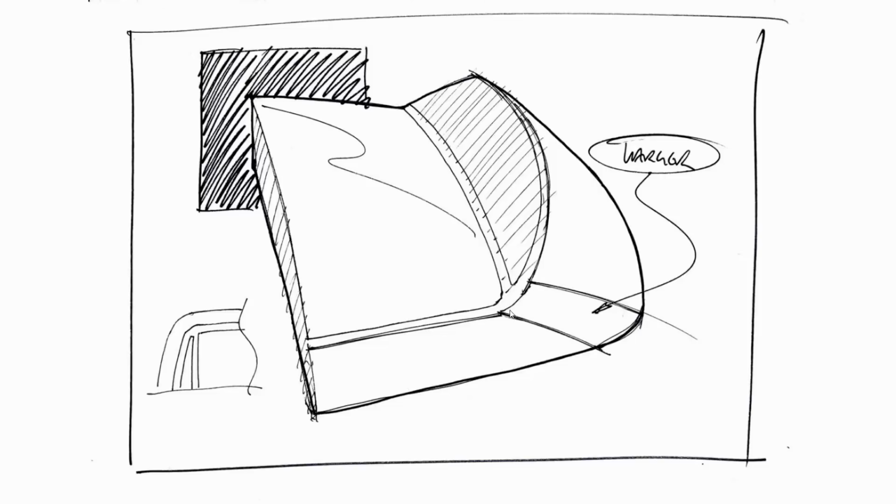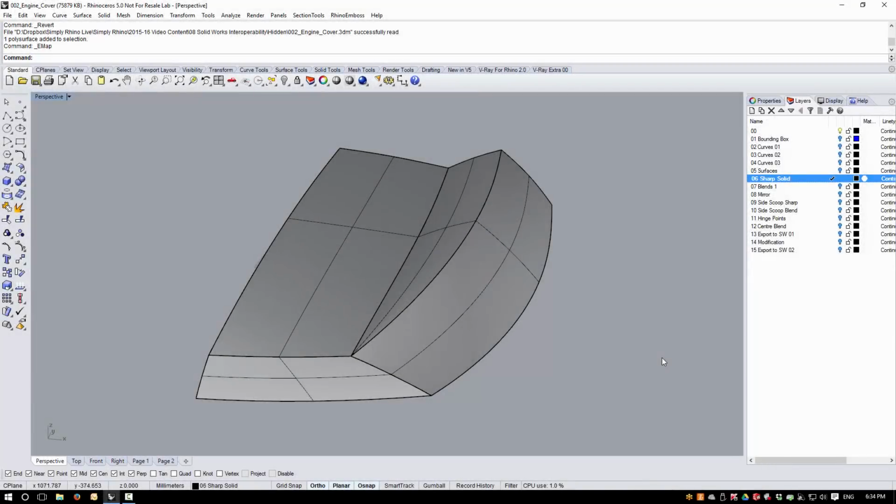Now, of course, how we actually create this transition is the difficult point, but what we can see here is the clear intent about what we want to do along the main portion of these blends. And this kind of mimics the way that we're going to work in Rhino. We're going to build the known parts of the blends first of all, and then finish up with the transition. Once we have the slab surfaces and the sketch reference, we can start to add the fillets or blends.